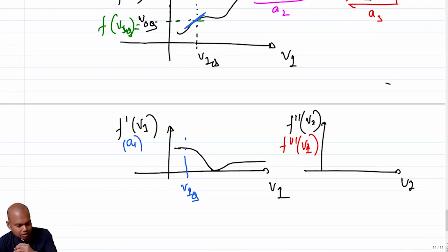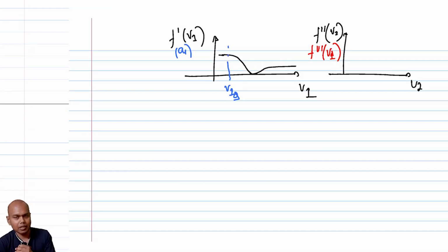But having said that, the very zeroth order principle that we learned in the last lecture, that is biasing at maximum overdrive, in general does the trick. If you can bias your transistor at the maximum overdrive, then in general you see that the distortion performances are much better than biasing it anywhere else. But having said that, there are other tricks to cancel out certain types of distortion, and we'll look into that in the coming lectures, right? Okay, stop.